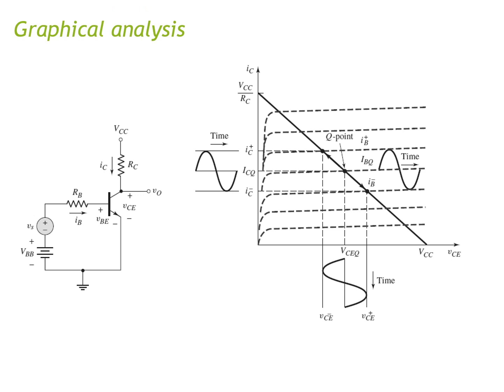So technically, the time varying current corresponds to the small signal Vs at the base. It induces an AC collector current that superimposes on the quiescent collector current. The AC collector current then produces a time varying voltage across the RC, which is the collector resistance, which then induces an AC collector emitter voltage as shown in this figure.